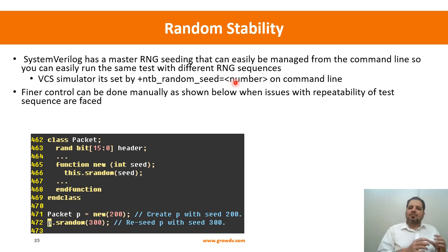A test that has a minimum amount of randomization, like we talked about, right? Randomization can be in terms of the sequence, or in terms of the individual parameter values that a particular transaction, which you are creating as part of the sequence, is taking. So how much randomization exists in a particular test? If it is randomizing both the sequence as well as the parameter values, then it contains a high level of randomization. So if you run it with more seeds, it's going to produce different types of behavior.